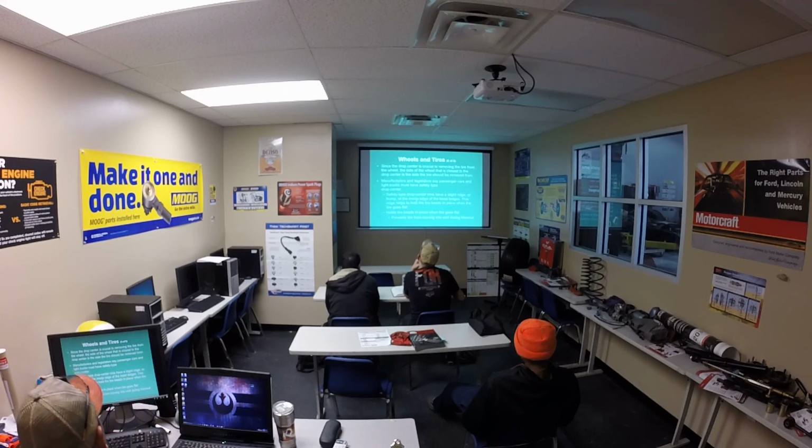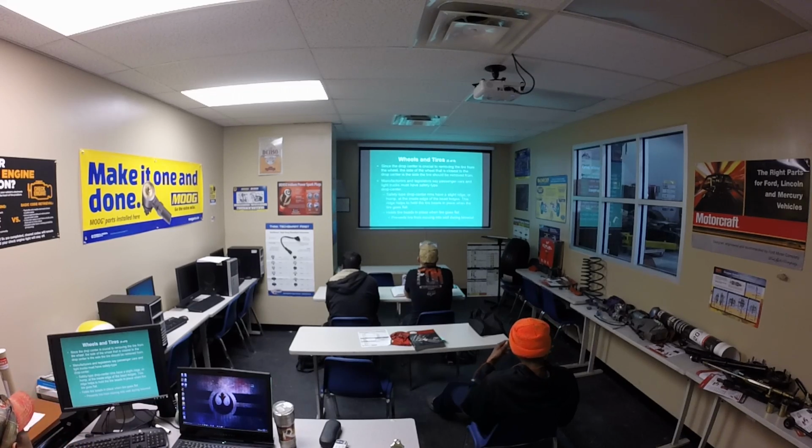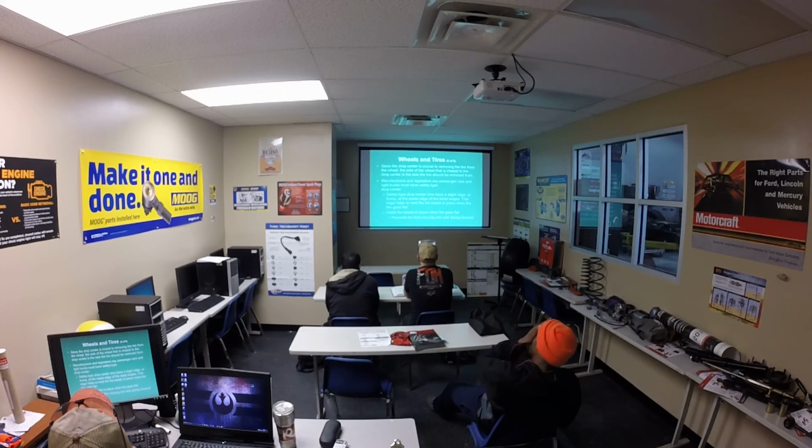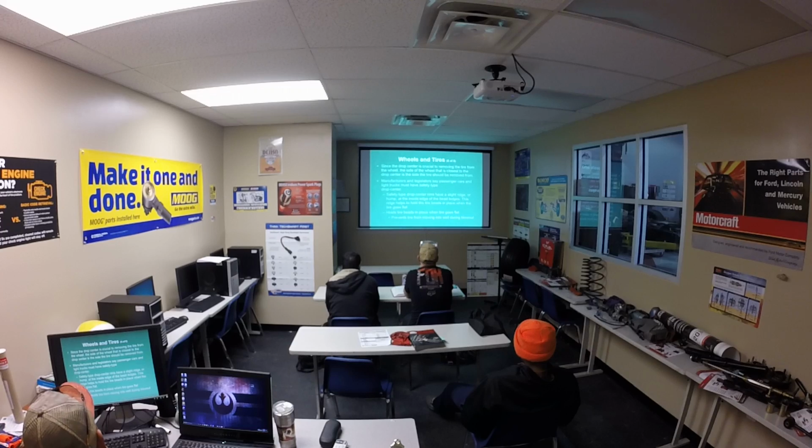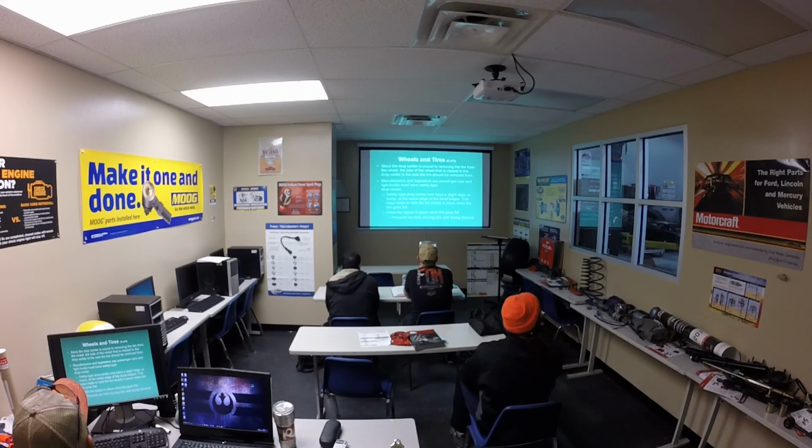Since the drop center is crucial to removing the tire from the wheel, the side of the wheel that is closest to the drop center is the side the tire should be removed from. Manufacturers and legislators say passenger cars and light trucks must have safety type drop centers. The safety type drop center ribs have a slight ridge or hump on the inside edge of the bead ledges. This ridge helps to hold the tire beads in place when the tire goes flat.